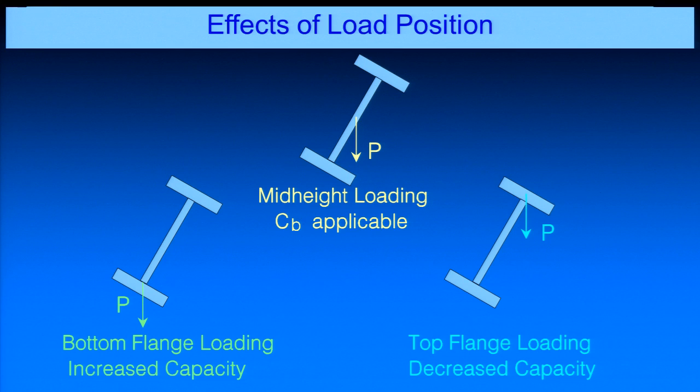If instead I have, say, bottom flange loading, the load's hanging off the bottom flange of the section, then what we're going to end up finding out is that as that section wants to twist, the load tries to straighten it out.